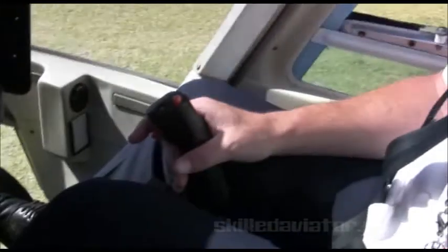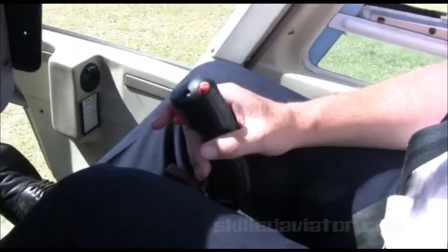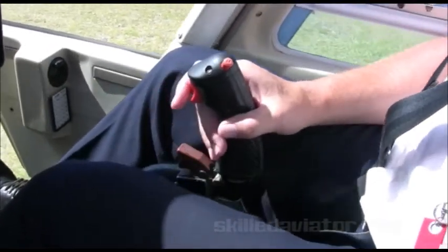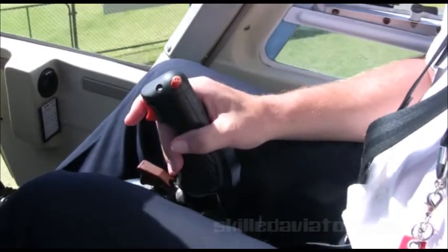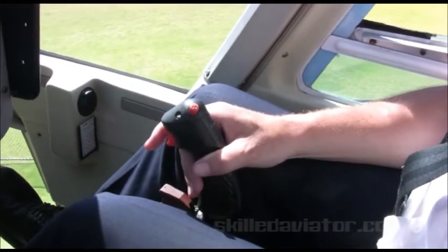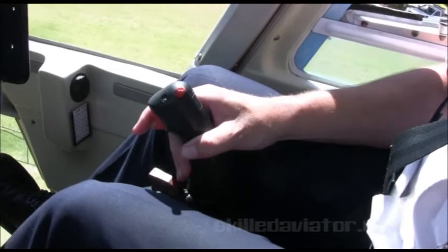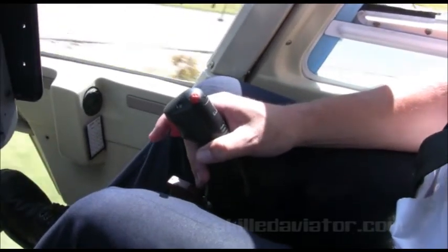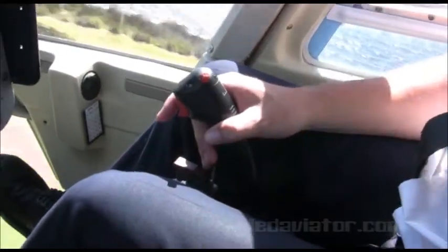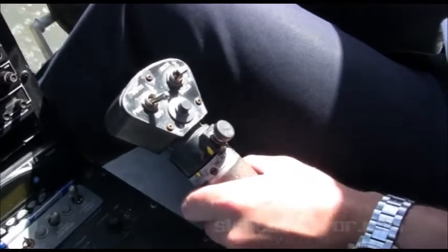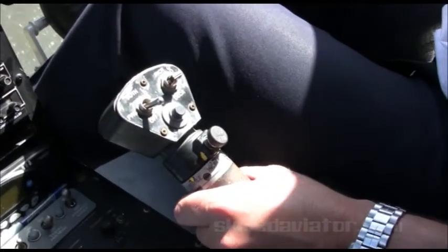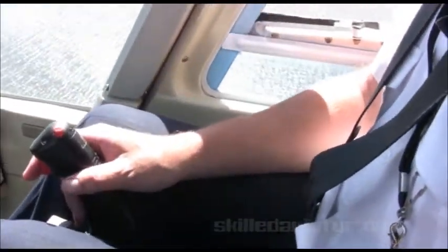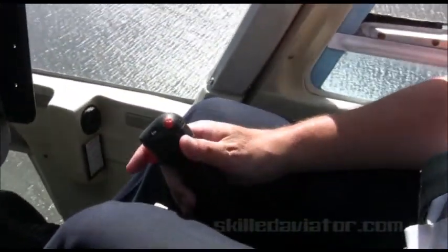When you hear the words, "you have control," grasp the controls lightly, ideally resting your right hand on your leg. Most students find they over-control and the helicopter will feel uncomfortable. The trick is holding the controls lightly and using the smallest of control movements. When you get the hang of it, you'll find you'll be controlling with your fingers rather than your whole hand or even your arms. The professionals describe it as flying by thought.